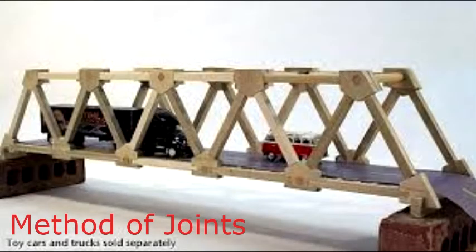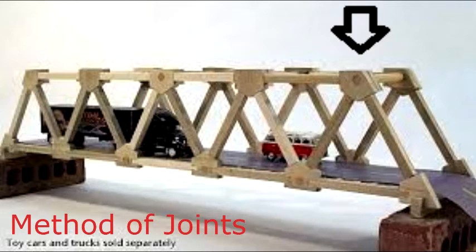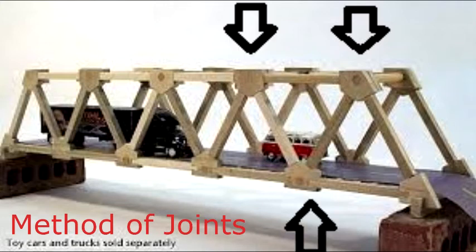Say you are to find the reaction at the middle joint of the bridge, when there are two cars exerting force downward. First, you get the reaction by drawing an FBD at the joint with fewer unknowns, and then the next one until you reach the required joint and get its reaction.